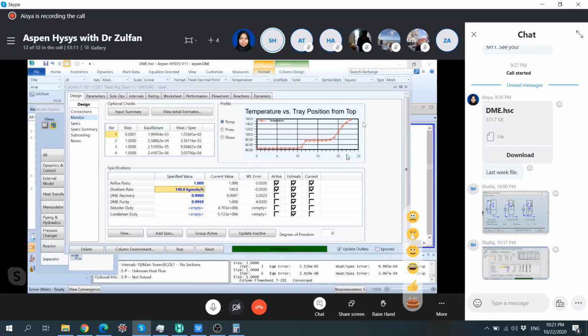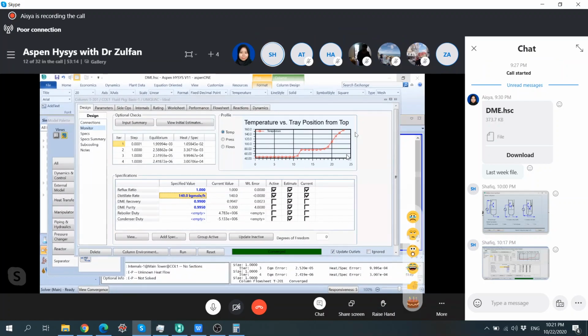So what we are seeing here is the temperature profile along the stages. When you dig into more information on this column, typically the efficiency will be by default 1 or 100%, but we will see that later. In separation, if you can still recall, especially in vapor liquid equilibrium, we know that the separation happens because there is a temperature difference.